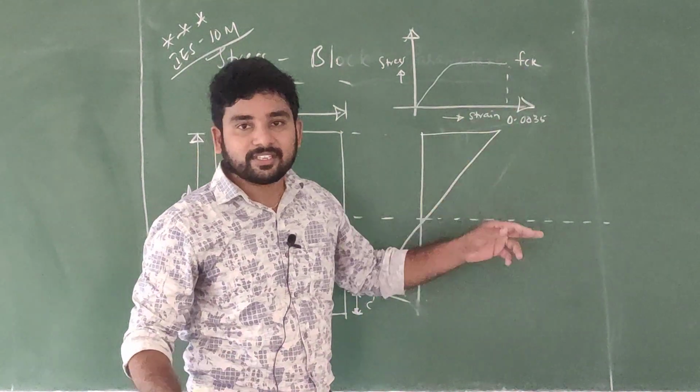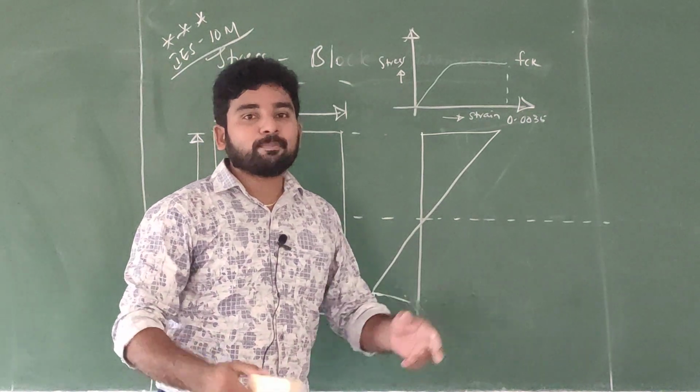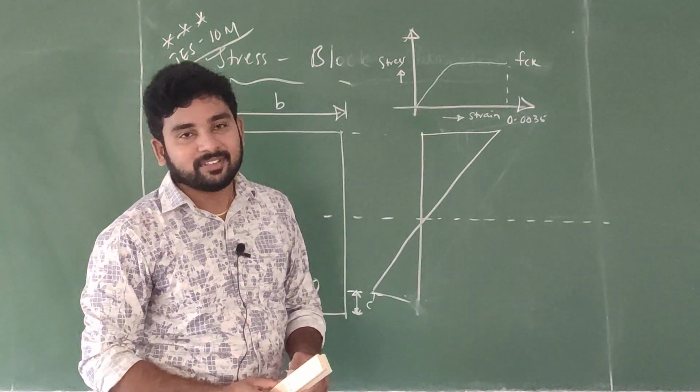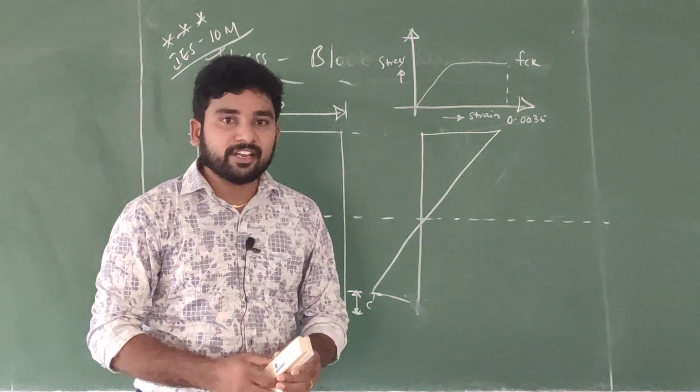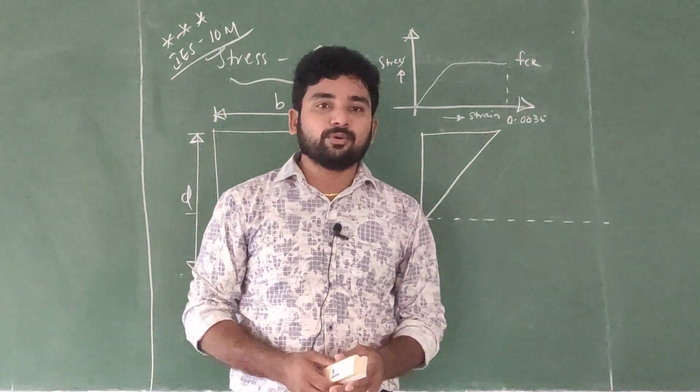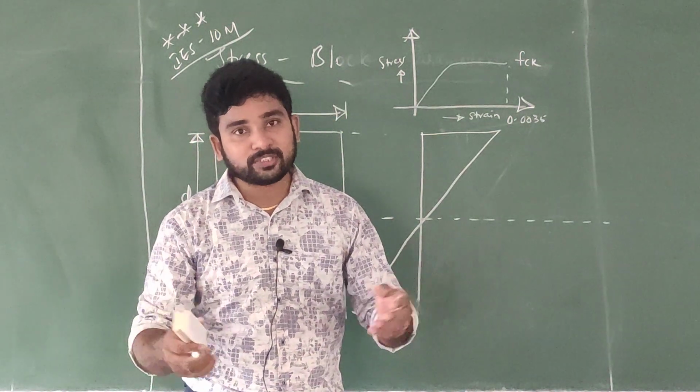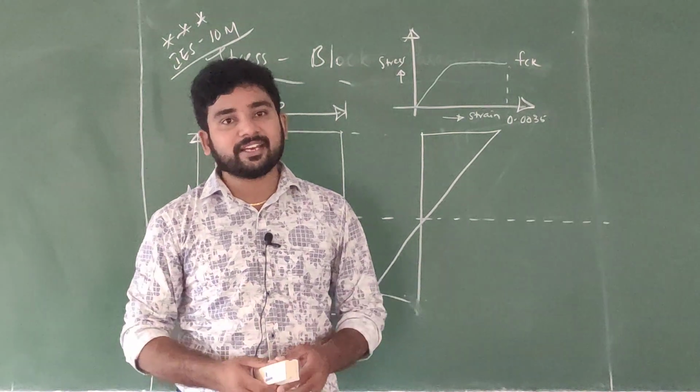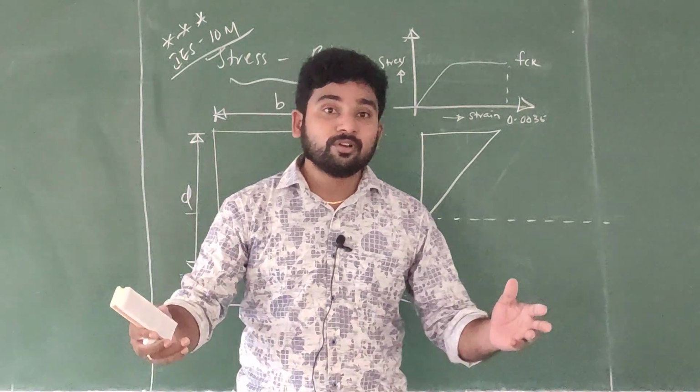Theoretically fck. Now we will apply the size and field-condition effect. In the laboratory, when you test the cube, you take sieved coarse aggregate, sieved fine aggregate, sometimes even mineral water.